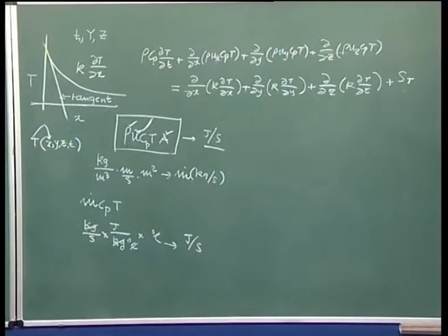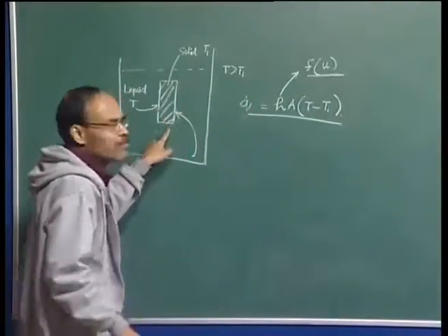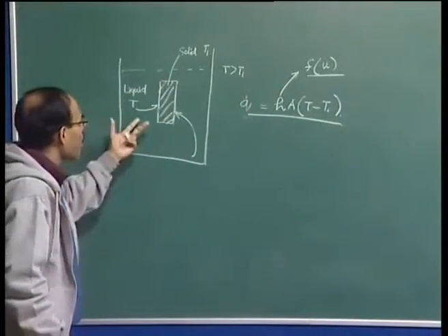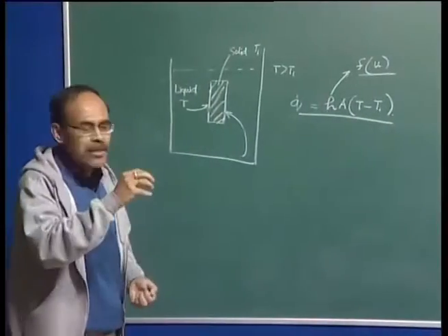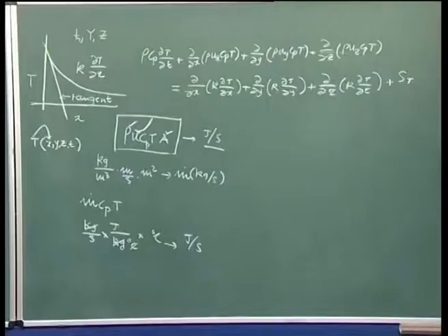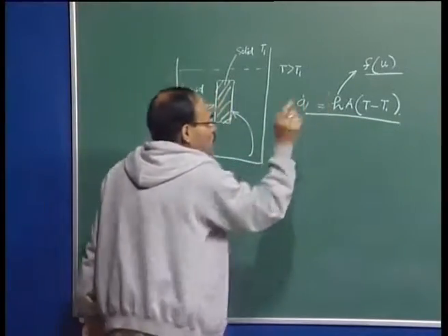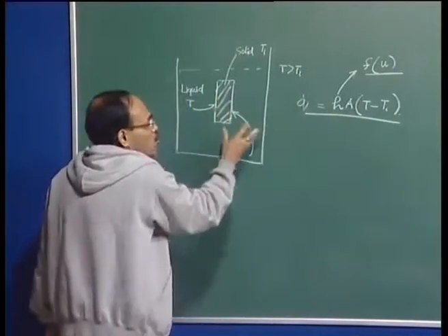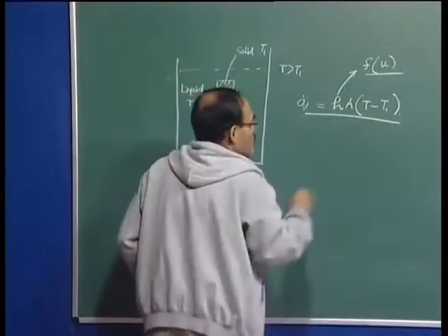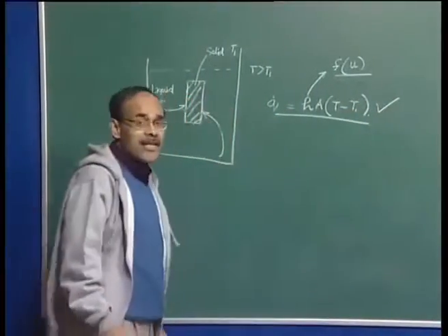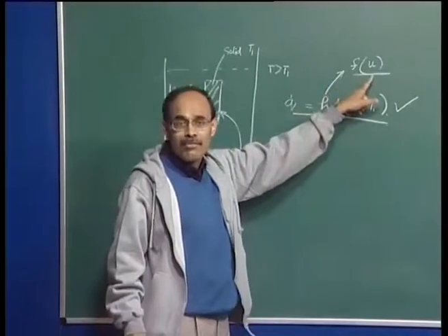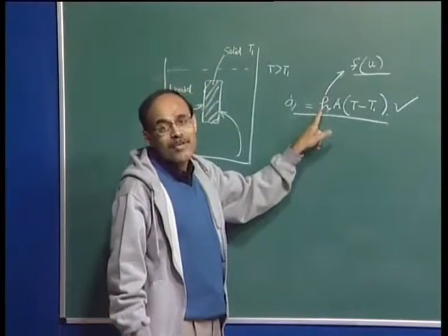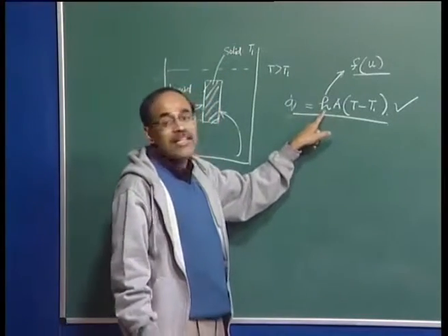So, this tells us that no matter what the problem is, even if you have turbulent flows, even if you have multi-phase flows, even if you have unsteady state behaviors in the system, it is possible that we need not solve those complex equations, but to express the heat flow to the solid surface, or from the solid surface, we can use this particular rate equation. But here the task is now how do you obtain the heat transfer coefficient, which is a function of fluid flow. The influence of fluid flow is coming into the picture through this small h term.